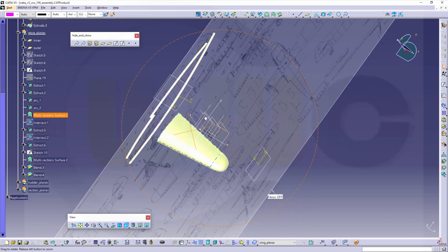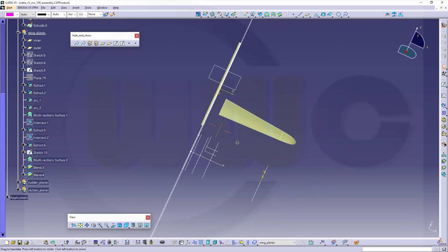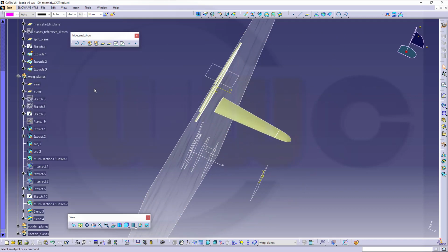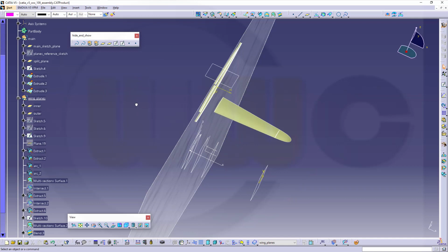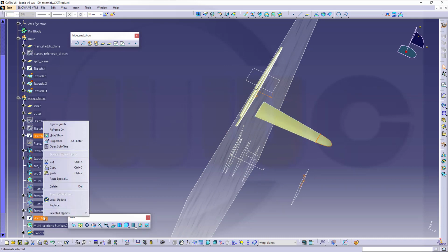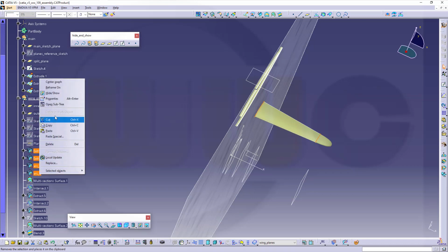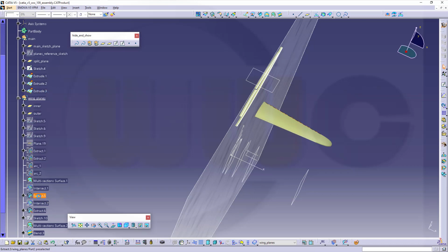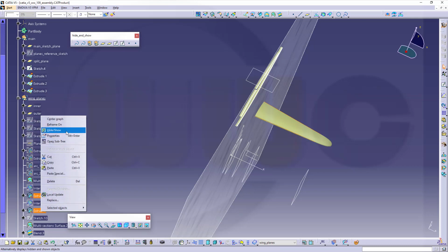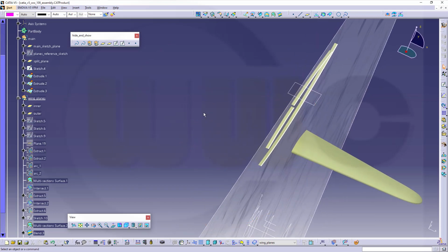Now I want to extrapolate this surface in that direction up to the mid plane, and that would be my main sketch plane. So maybe hide the sketches, this one and that one, hide those extracts, those as well. Now let's try to extend that. So go for extrapolate.